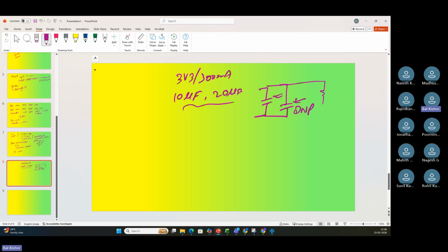So you have a provision of additional capacitance, a capacitor bank in the circuit, so that you do not land up in a situation where you do not have a place on the PCB to add more capacitors. That is a very good design practice of having extra capacitors placed. But do not go overboard with a lot of capacitors, don't make it capacitor land. Be very specific: I want one is required, but I have put two. Don't put 5, 6 and all because I want additional, like information or something like that. So there are no other reasons.